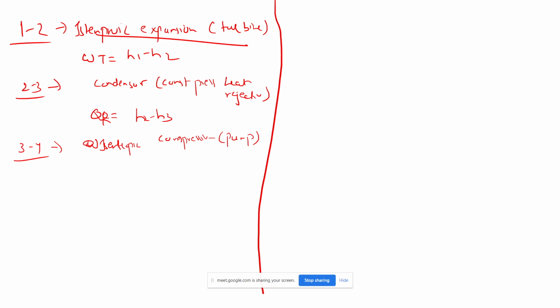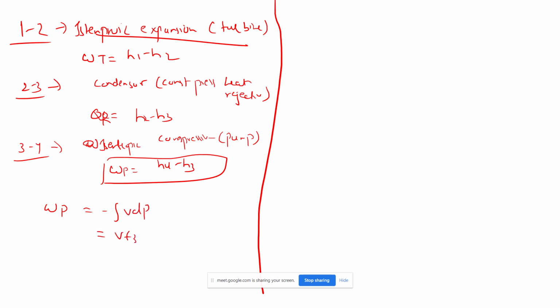So what will happen? Enthalpy will increase. h4 minus h3, the enthalpy change for the pump, will be like this. Also here, because for the pump, as I have already discussed, the integration of v dP is there, so we can represent directly like this: P higher minus, after integrating, P lower. So we can also write like this if you are not given the values.